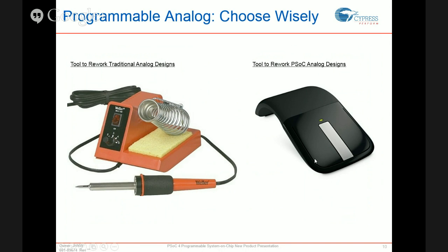PSoC Creator is an extremely powerful software tool that's got a complete visual and schematic-driven interface, and it gives you the power of using your mouse and your computer to create analog and digital circuits rather than the soldering iron. It has advantages because you can go back and rework things and simply reprogram the chip and not have to go back and resolder your development hardware or your prototyping kits and so on and so forth. And we'll see how we do that today in the tool live.